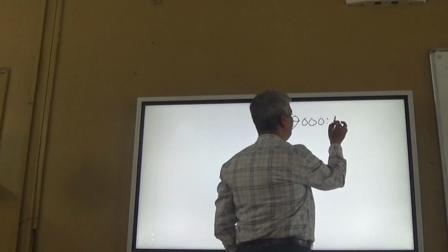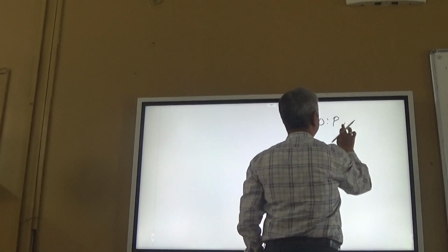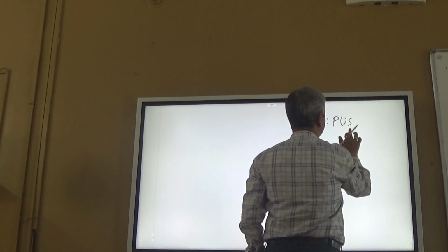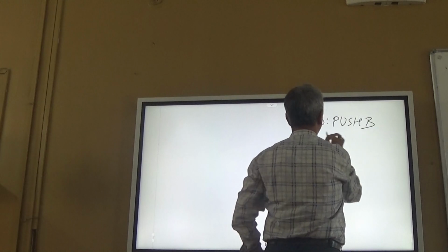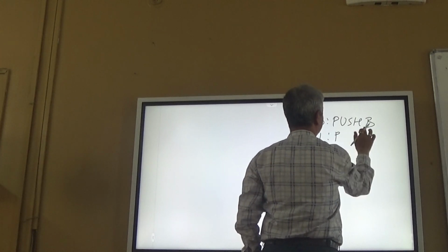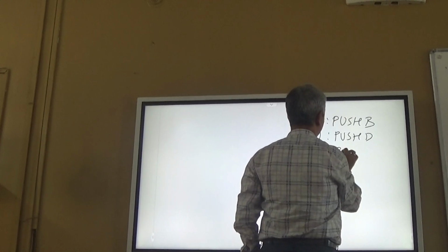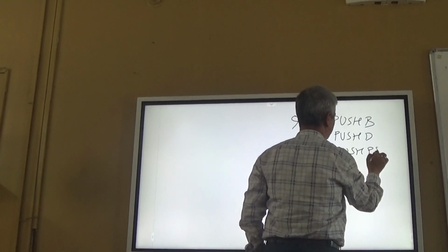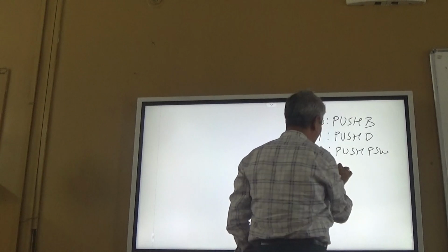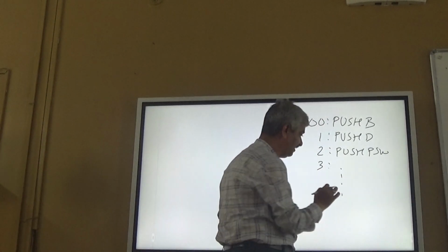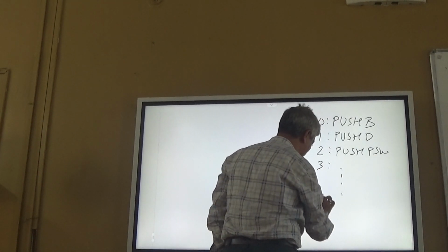How? Push B at 9000, then at 9001 push D, at 9002 push PSW, then from 9003 my actual program will be there, and when my program is over at say 9013,